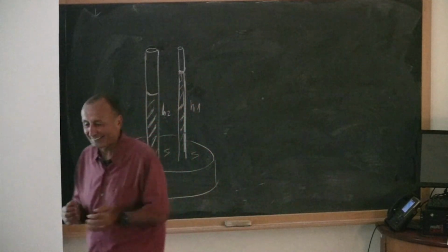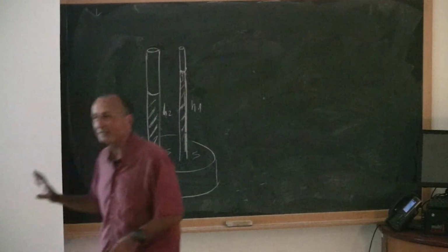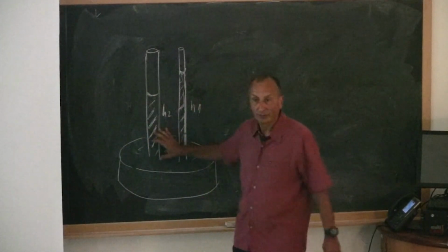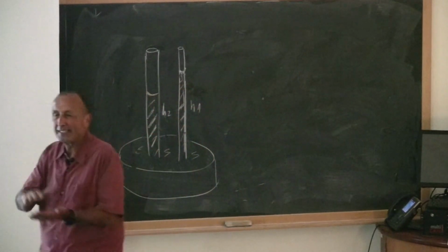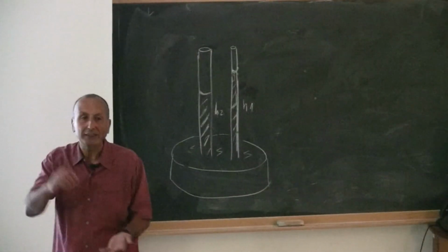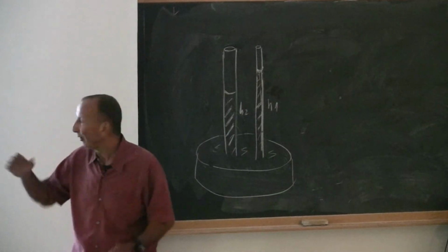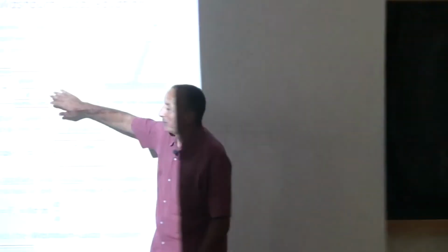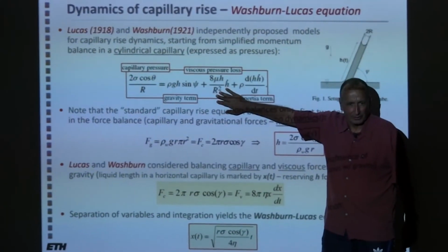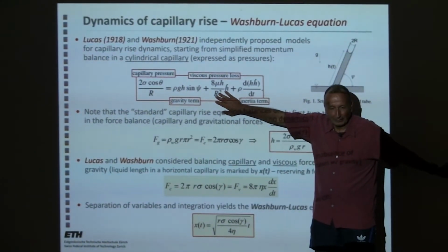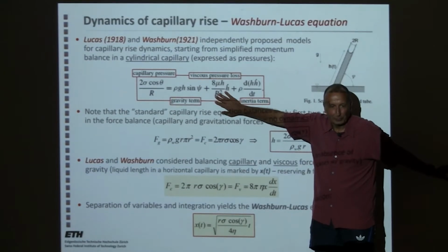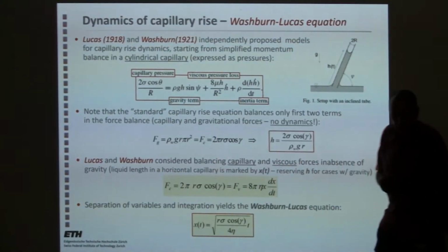excellent. It's not so. The answer is that the large one will arrive first. The reason is that the rate of capillary rise involves, as I indicated, some other forces. So viscous forces, which are reduced in the large capillary, will contribute to its faster arrival at equilibrium.